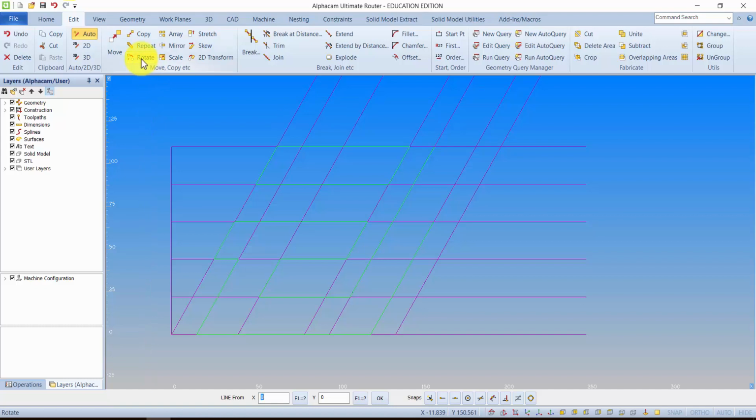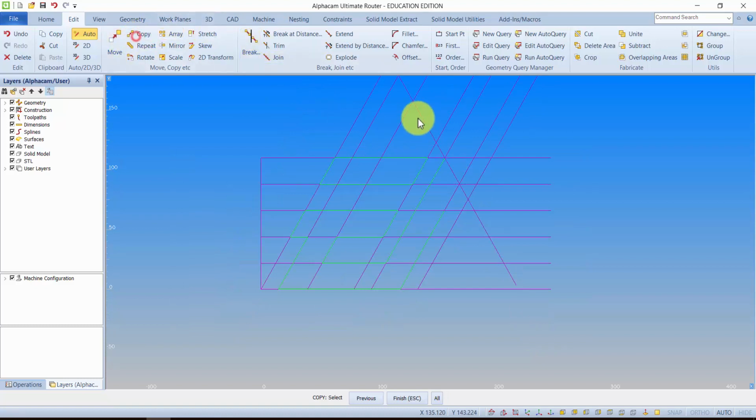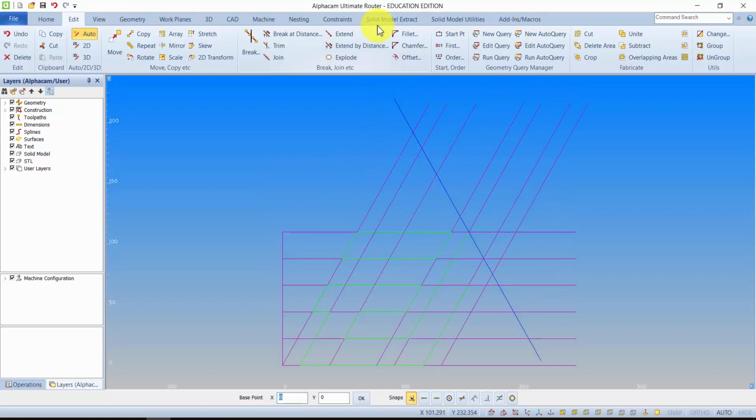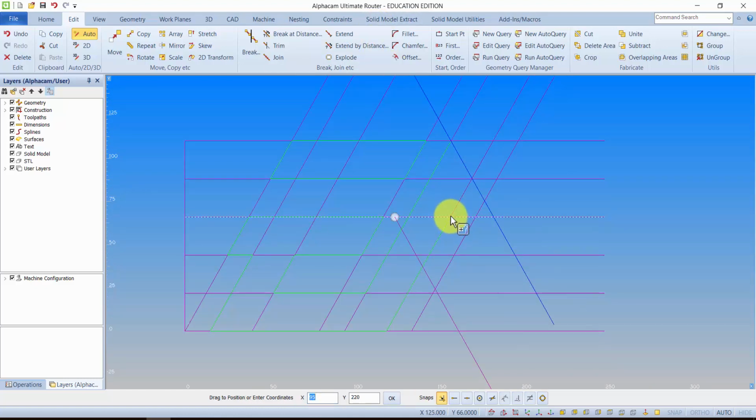I'm going to go to Edit, Rotate this line about, let's turn on the snap, about that point, and the angle I'm after is 240. So type in 240, enter. How many of them? 2. Okay. Now if you happen to have had a line going down already, you could have just copied the line, pick it up from any particular point. I'm going to pick it up from its end point, which I do want in this case. I want another version of that here.